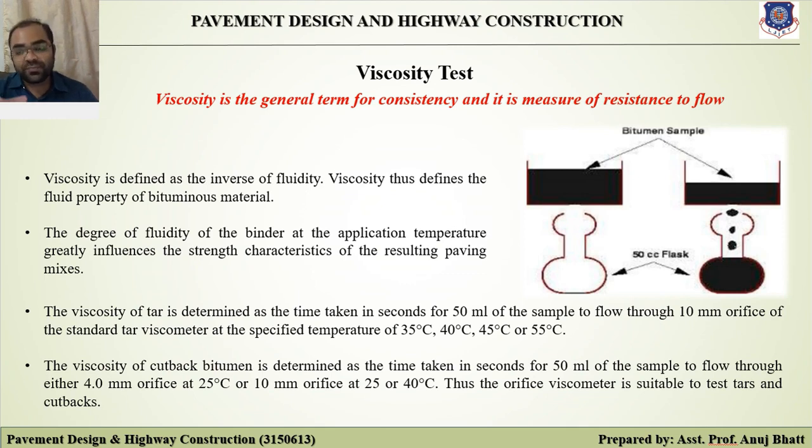As per this test, the higher the time taken by the bitumen to fall down into the flask, the higher the viscosity of that particular bitumen material.